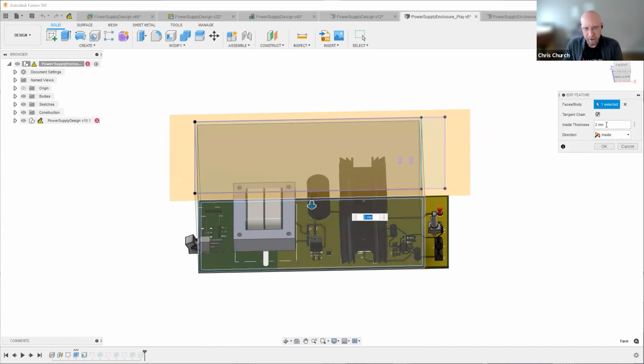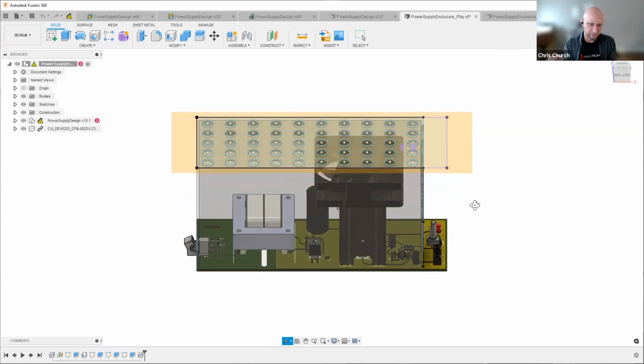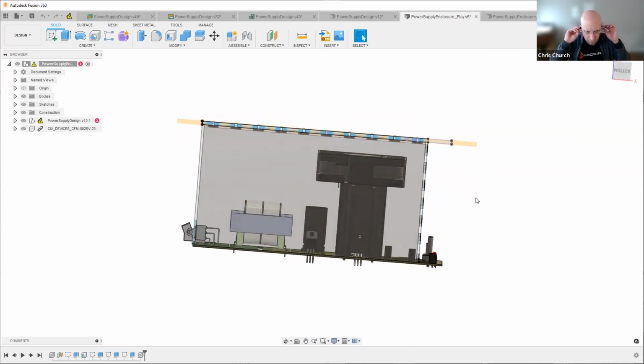Using 2 millimeters, right? So a typical fan, I think, uses an 8-32 size screw, which, if I recall my rules correctly, and our engineers are better at this than I am, needs around 3.5 to 4 millimeters of minimum thread connectivity. So we don't have enough space to thread in there and offer a viable connection. This is where our typical design for manufacturability team would come in and give this feedback.